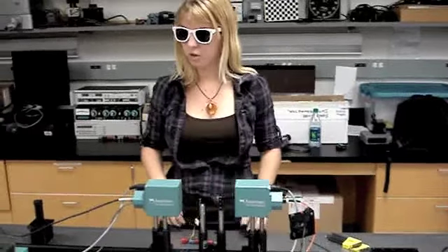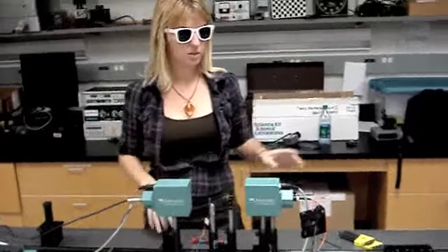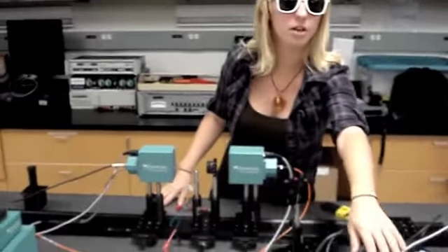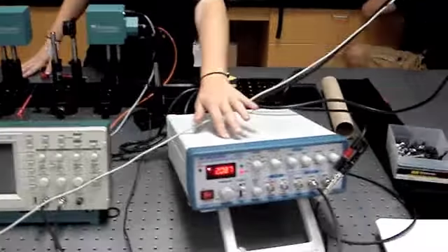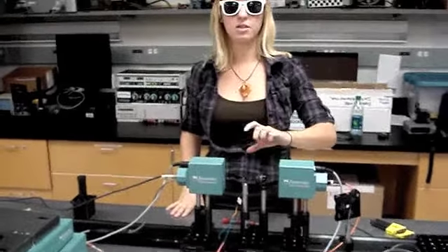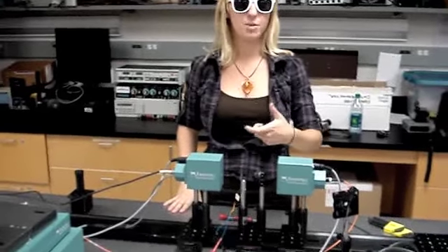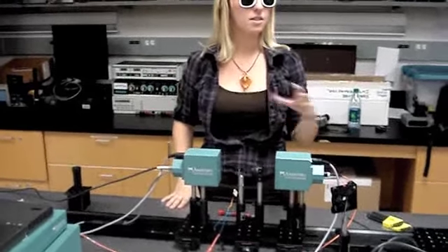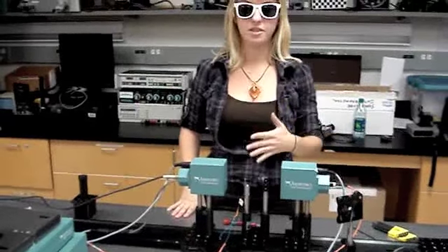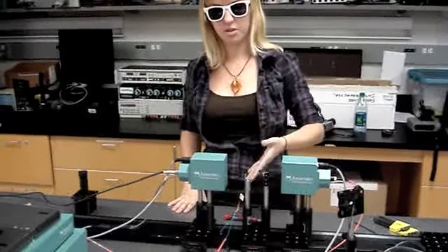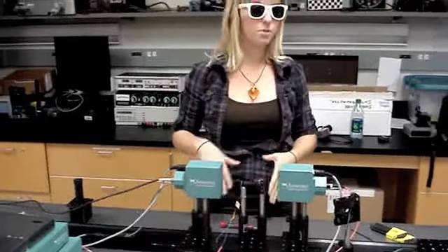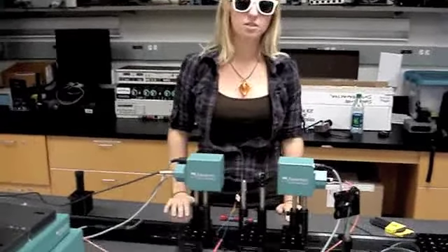When we were creating our signal for our system, we used a 2 kilohertz sine or square wave because our LCCs cannot respond to a wave of that speed, so it sees it as a DC signal. But if we apply a DC signal, it can actually damage the LCC, so this is our way of recreating that without damaging the LCC.